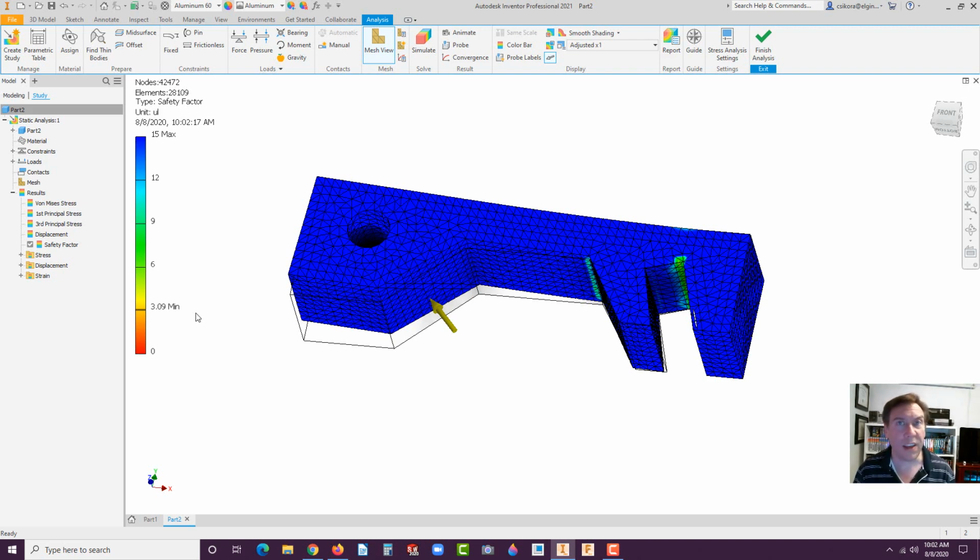Be aware, though, that like the aerospace industry, remember, they have to launch things into the air, and the heavier it is, the less efficient it is. And so they might actually work off of a 1.5 factor of safety. So this is twice that. So it might not be desirable. So, well, it's too thick. Let's thin it out. Let's change it.